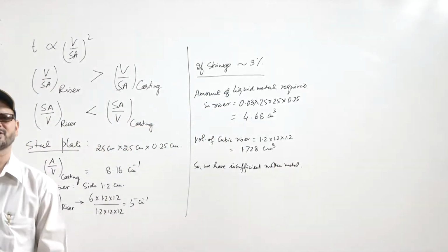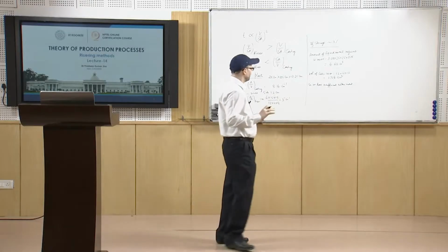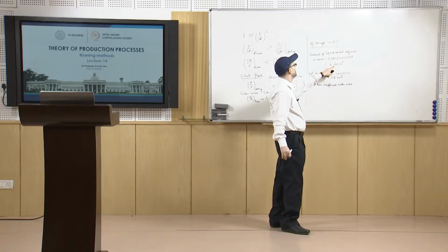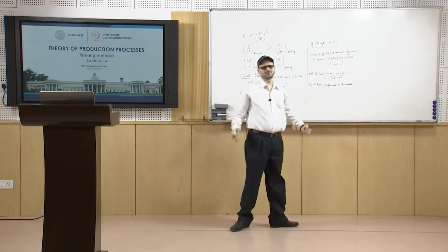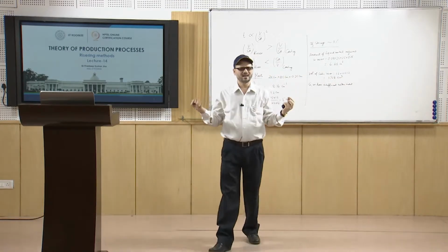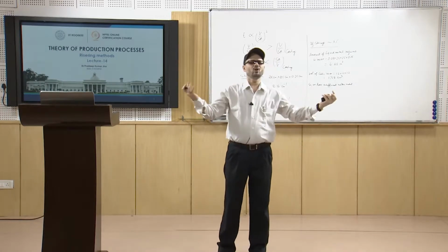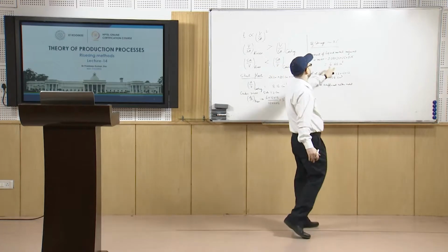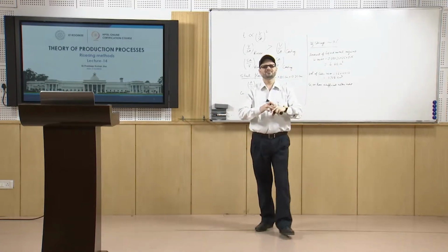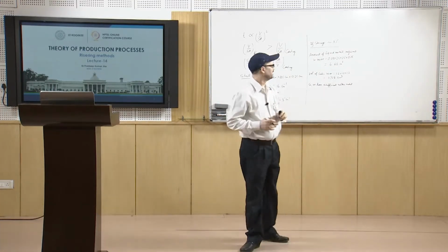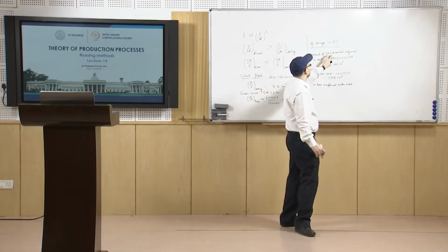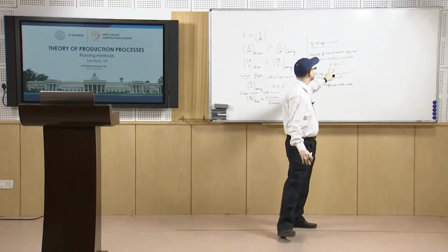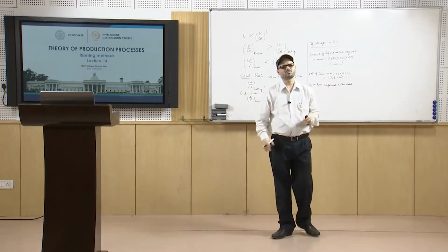So, this sufficiency condition is not met. In fact, you will have to have the volume more than this, because the riser is also a casting and that will also solidify. So, for this much volume required, you need an even larger dimension, a larger configuration, so that it can release at least this much liquid metal if required.